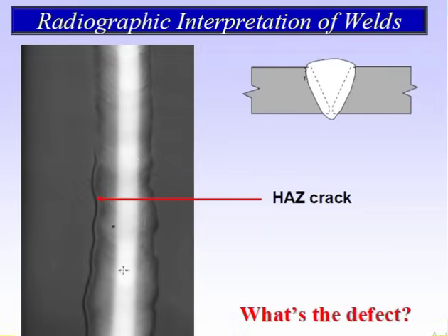You see this crack. This crack happens in this area continuously in the parent plate. So you can see the cap area, there is the parent plate, there is a crack. You can see the parent and the heat affected zone. This is your HAZ area, 25 mm, it is the HAZ area. So in the HAZ area there is a crack. It looks this way, this is called the HAZ crack.